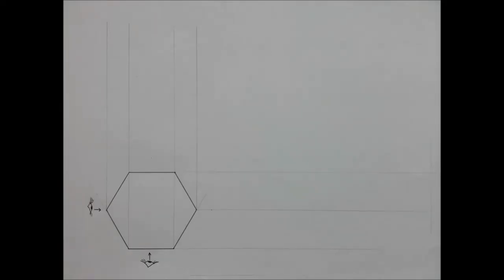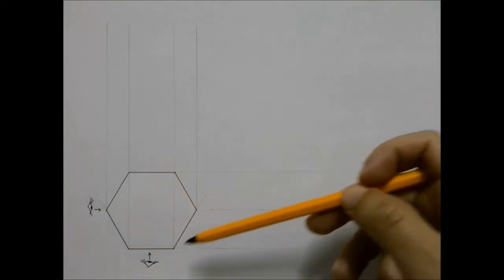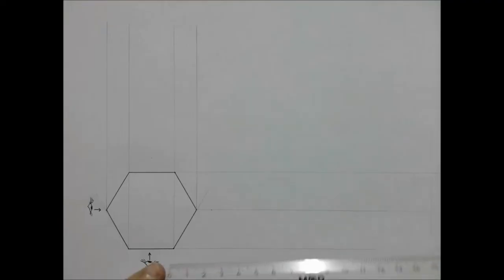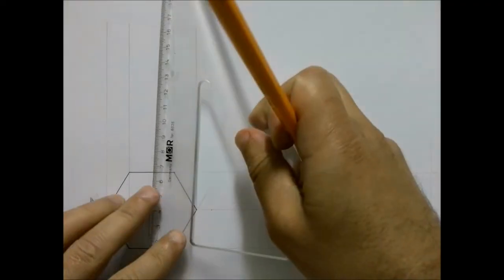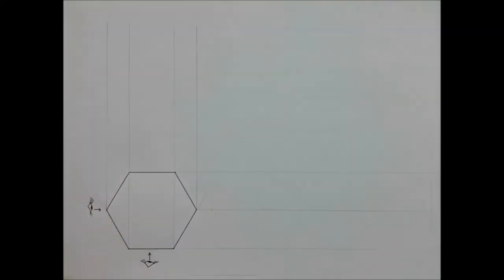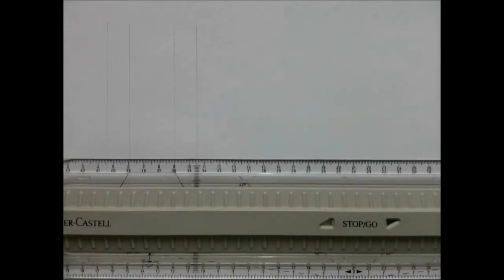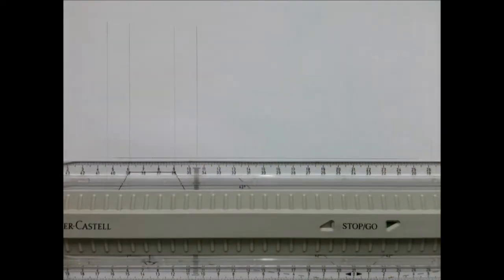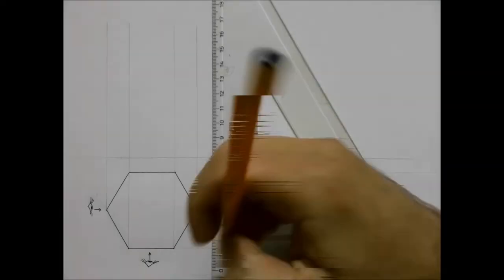Okay, so my suggestion to you in this video here is for you to first go and draw your top view before you include your axes. Alright, so I've gone ahead and I've taken the 10mm axes, 10 millimeters away from my drawing. Okay, and now I'm going to include my axis or axes. Now please go ahead and go and construct them at first, because you don't know how far or how much of those lines you'd need just yet.